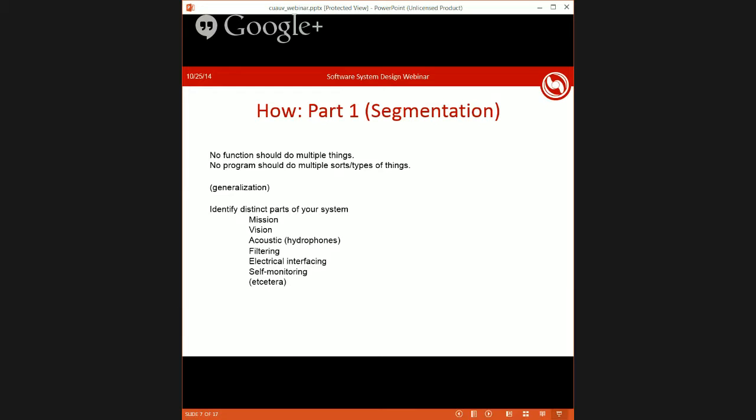You might have electrical interfacing, such as systems that interface with any electrical stuff on your submarine. Maybe that's thrusters, actuators, some of that could be involved with sensors. And again, you want the code that allows your computer, or whatever you're using as the brain of the submarine, to talk to the camera to be separate from the code that actually translates the camera information, the pixels, into object information, because then you can replace one without replacing the other.